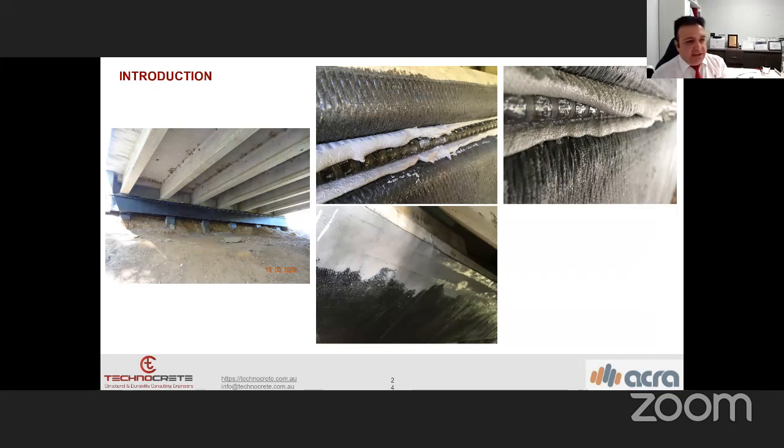As you can see in the middle top photo, we have an FRP rod inside that anchorage, completely covered by epoxy. The right-hand top side of the photo shows the FRP rod, which can completely lock the CFRP wrapping into the substrate so it is fixed. And in the middle bottom one, you can see the finished work of the anchorage system.